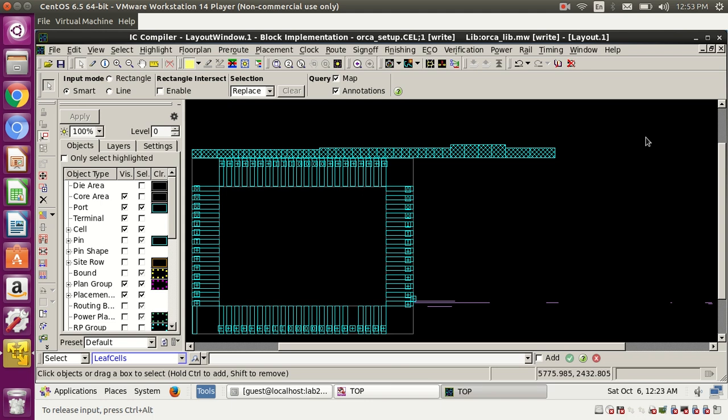So why do we have to go above? Because we cannot route our design in one metal layer, we go to a second metal layer. Since we have complex designs, we cannot route in M2 also, so we go to M3. But we have the clock, which has to be even faster, so we go for M4, M5. Even the clock we cannot route in M3, M4, M5, so we go for M6, M7. But we have the power mesh, and we have to make power more optimistic, so we have M7, M8, M9.